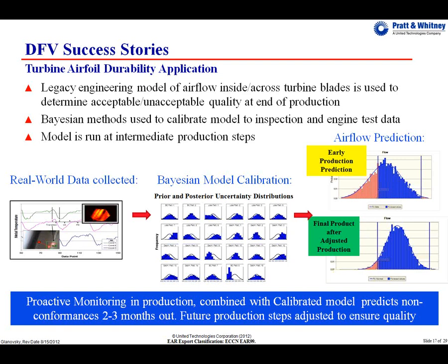But given what I just said, you can probably understand how it's extremely important that we put those holes in the exact right place and we make them the right size so that that air skin is kept at proper thickness, proper temperature. If you have insufficient, even just over one small part of the blade, that part's going to start melting away. And guess what? The engine will probably still work, but this just means you're going to have to remove it from the aircraft when you find it, take it all apart, take the turbine out, put a new one in, and here comes your new repair bill. Best if we can avoid that.